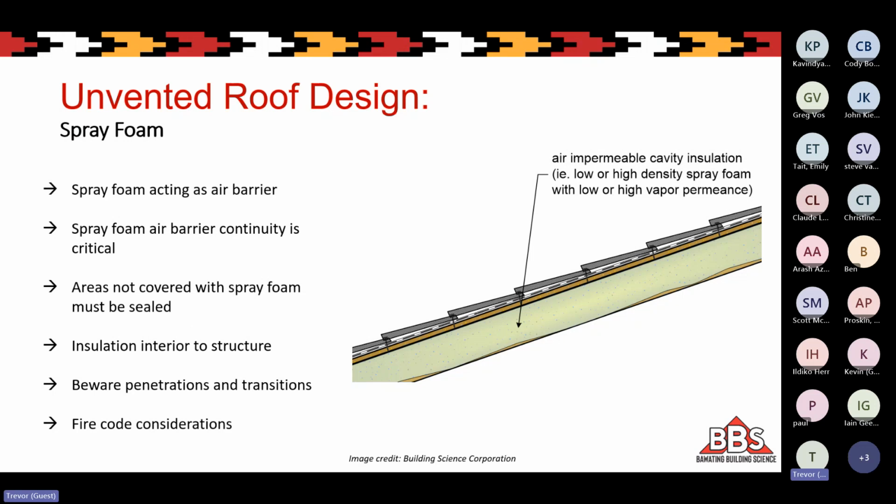So this can work really well, but there are some specific caveats to that, in that the spray foam installation has to be done very well in a very airtight manner, and other air tightness measures have to be taken.